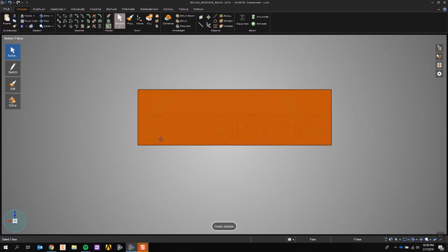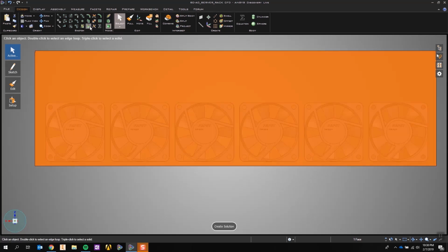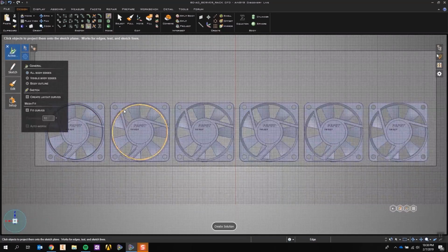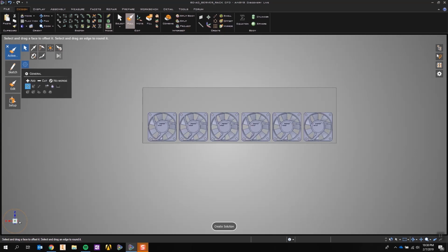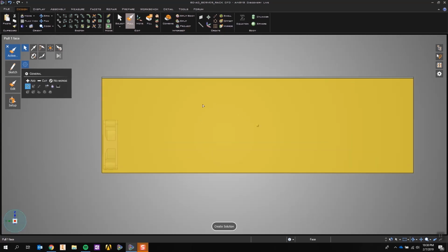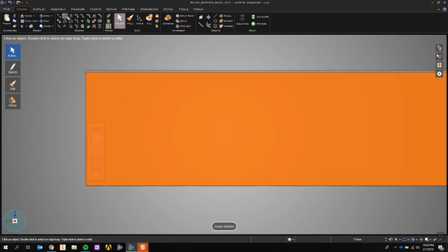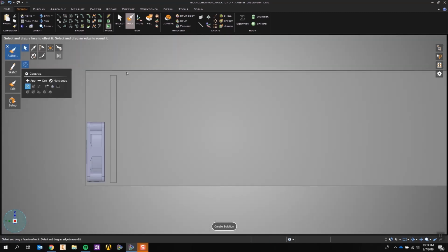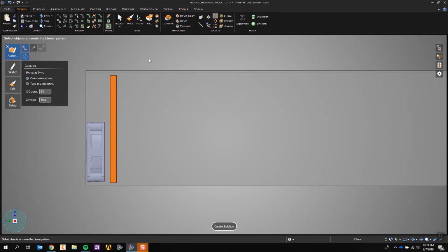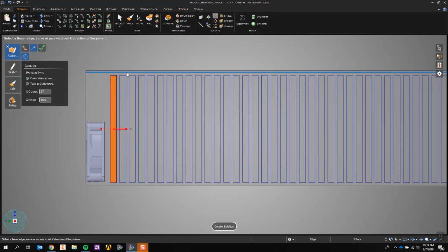Modeling the fans onto our fluid domain is quick and easy. We can project the fluid flow areas of the fans directly onto our fluid domain. Even if we don't have vents pre-designed, we can quickly conceptualize a vent pattern using the Discovery Live design features. Any sketches made on a surface will form split lines onto that surface. These split lines can be used to apply boundary conditions such as forces, temperatures, or fluid conditions.